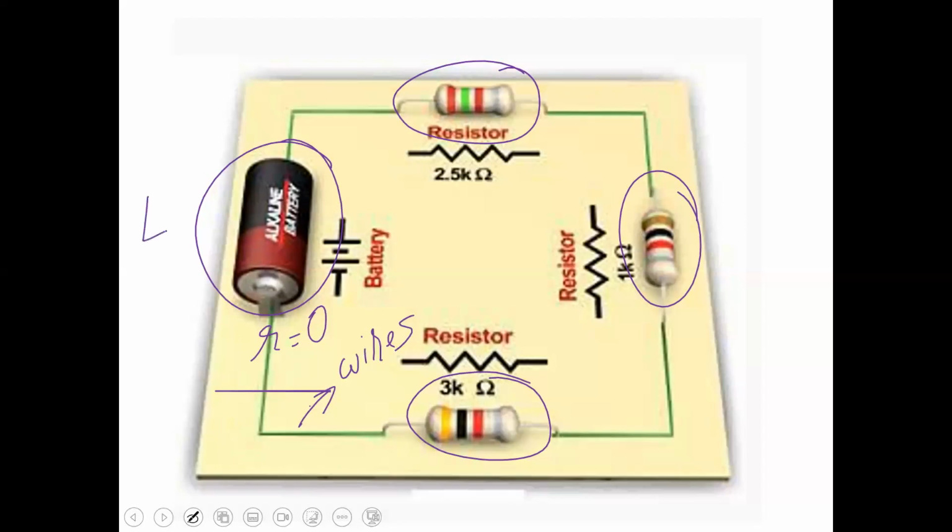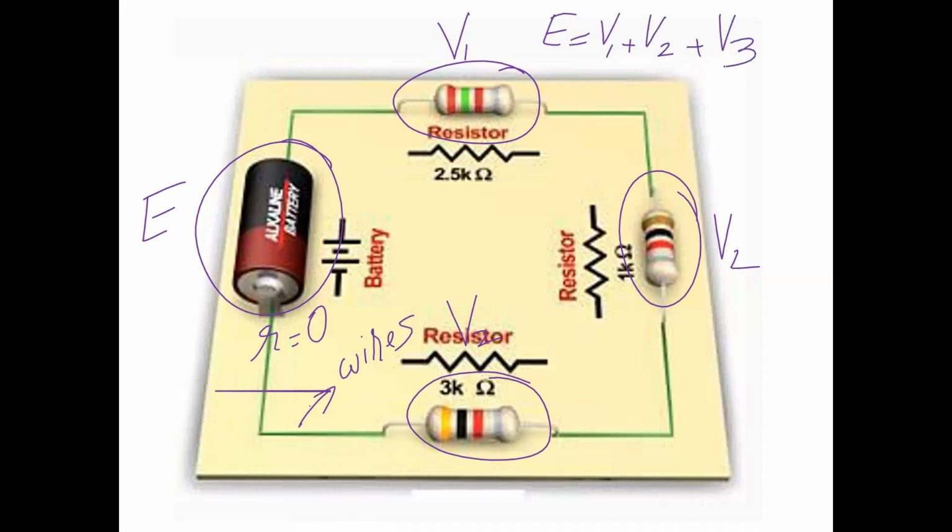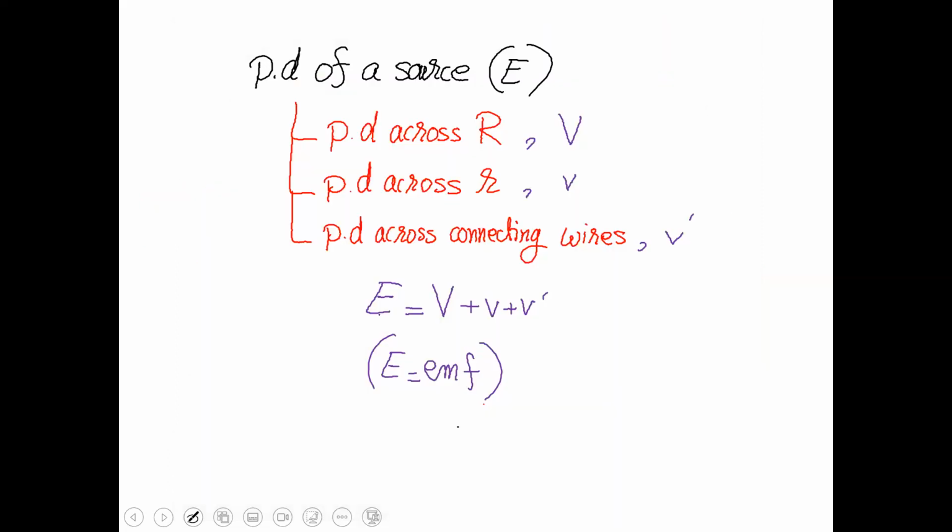Now, if the power source has EMF E, the resistors will take some voltage each. Logically, it's dividing something in a line. So EMF will be equal to V1 plus V2 plus V3, assuming there is no internal resistance in the circuit and assuming there is no voltage loss on the connecting wires. So this is the spectrum. Who are the contributors? Who are the shareholders of the voltage? Now you have to give a side heading, second law, and copy this.